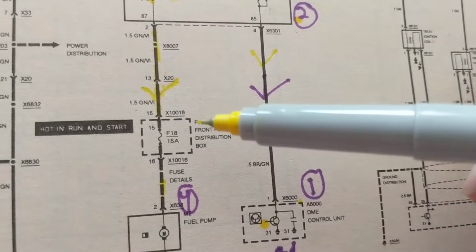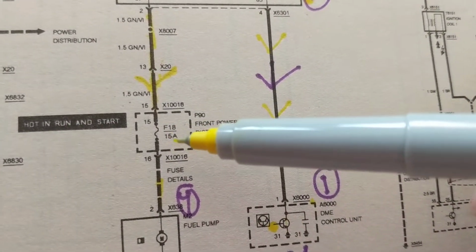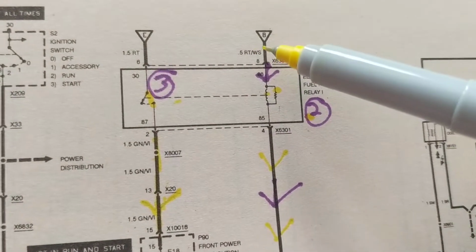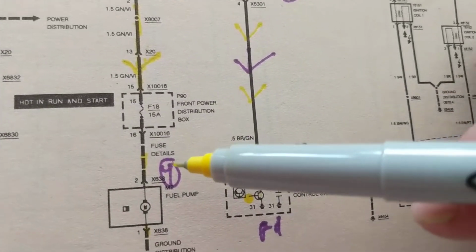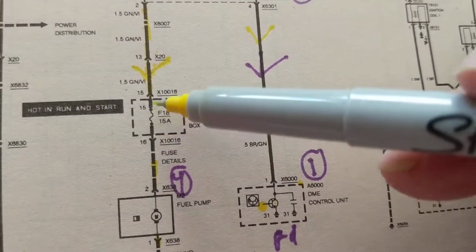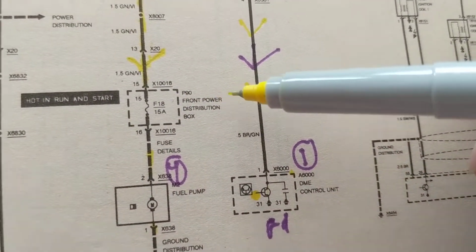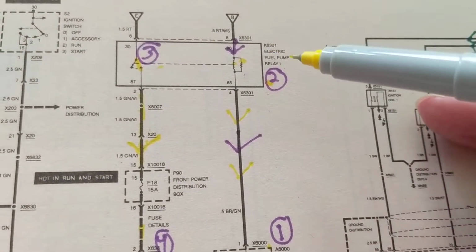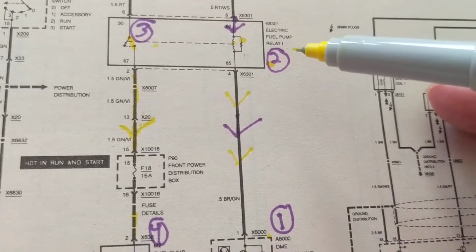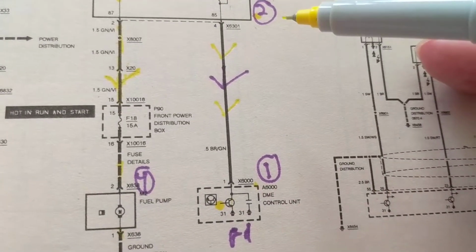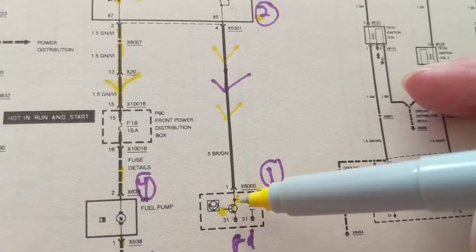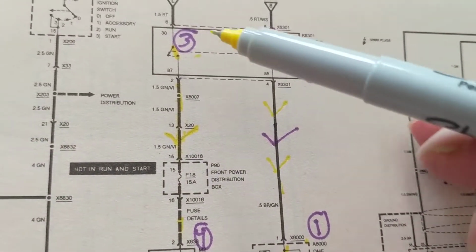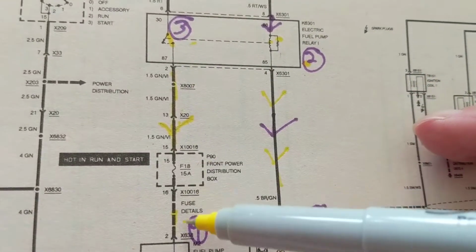Very important. As you see over here, there's a fuse, and the fuse rating is 15 amps. The fuse sometimes could be over here. The fuse could be over here. Before a motor, we have the fuse usually. Okay, very confusing, but that's how an electric fuel pump works. Remember, I could put a ground over here instead of a transistor. Current flows here. That allows this part of the circuit to flow.